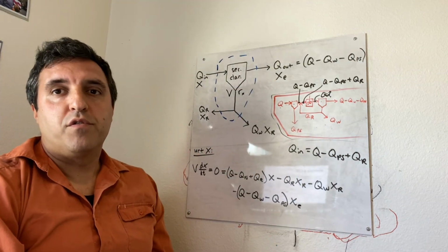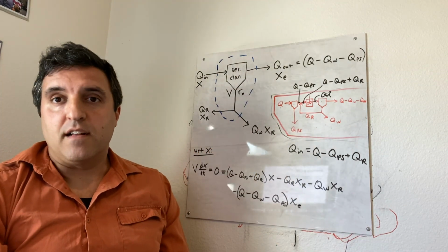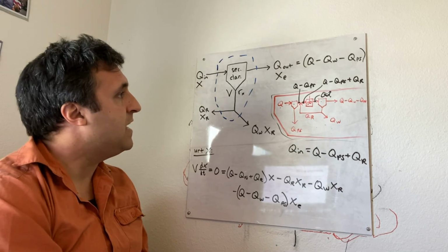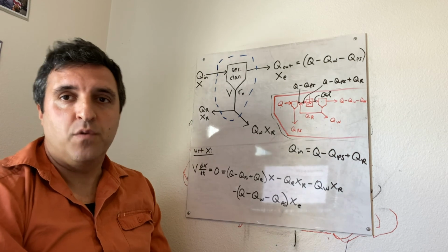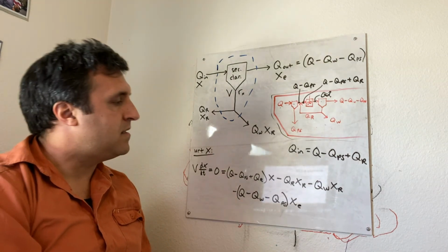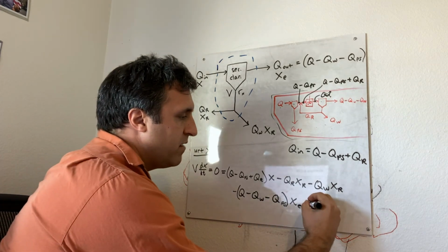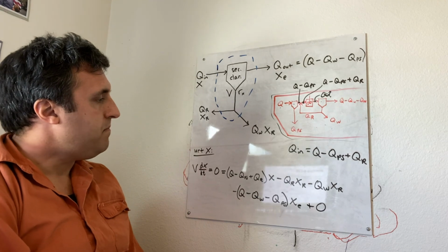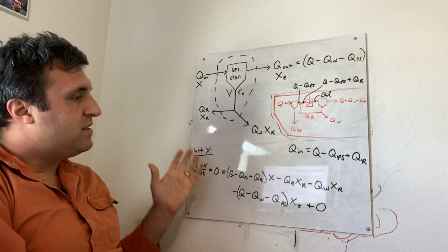We can assume that the growth rate in the secondary clarifier is negligible. This is not a reactor where we are feeding the wastewater with oxygen in order to promote the growth of microbes. We're just letting the biomass settle to the bottom. So we can assume that growth is negligible in this reactor. All right, so that's our mass balance.